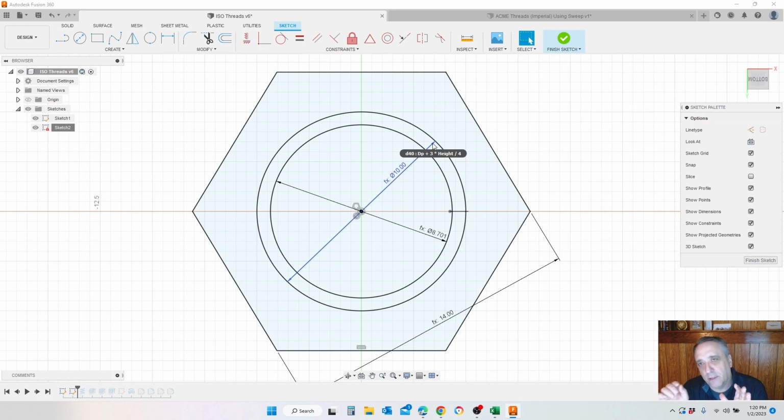So you know where we had that little height over 8, whatever. It's basically going to make sure that this gets cut out and cuts that part out. And then on the inside of this is 8.701. I have that as height, d min minus height over 4. And what that is, that's to make sure, if you noticed, on the inside cut of those threads, it's also flat. So it's creating a cylinder along there that can get combined with this. So you kind of see how that goes here in a second.